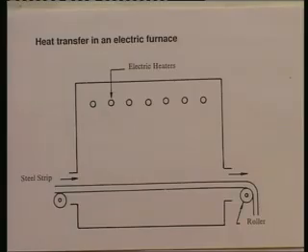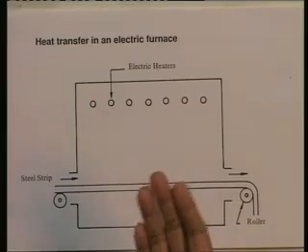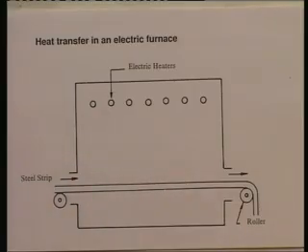Now, during the rolling process, because of the deformation that has taken place, the steel loses certain desirable properties like ductility, malleability, etc. We want it to regain these properties, and typically for that one does some kind of an annealing heat treatment process.